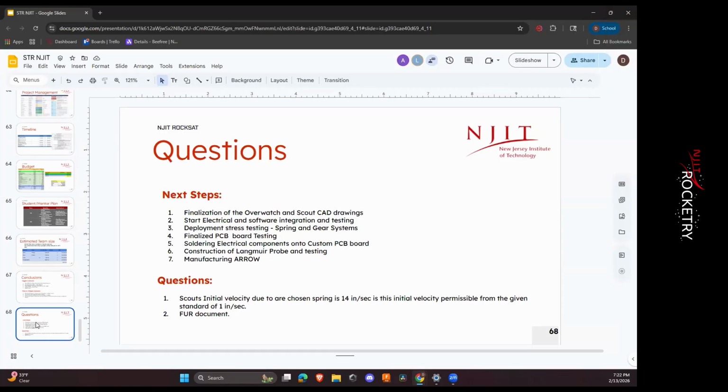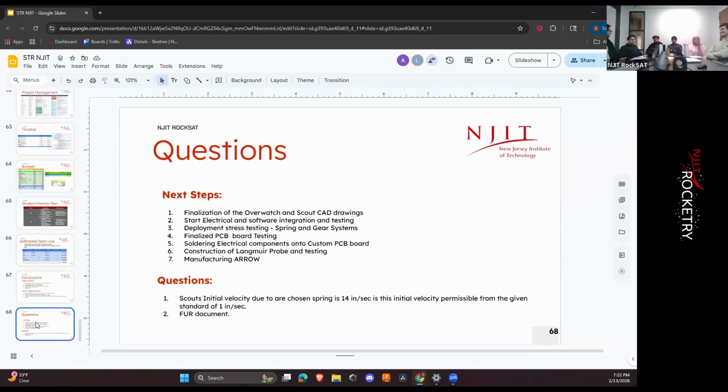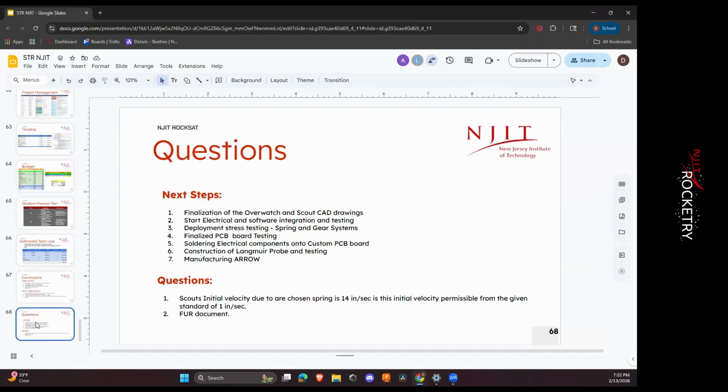Hello. Sorry, I have a quick question. Sure. So yeah, we agreed that the 65 amp spike or the more realistic 27 amp spike will not trip the fuse. But we are trying to move away from the polyfuse because we found out it's temperature dependent in its operation. Obviously, when it's going to be up in the stratosphere, it's going to be really cold. Is there a more standard fuse that you recommend we look into? Because right now we're looking into a slow blow ceramic fuse.